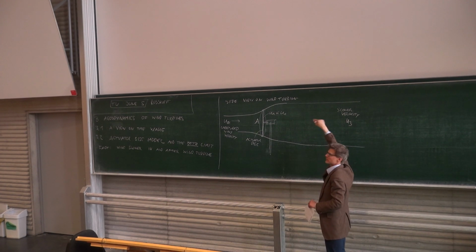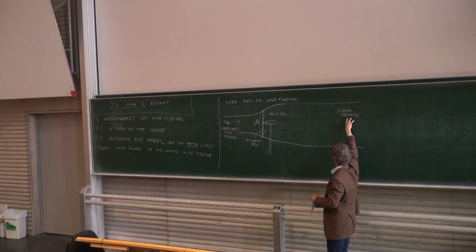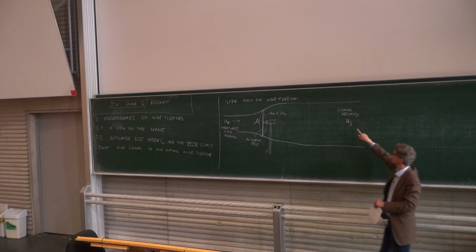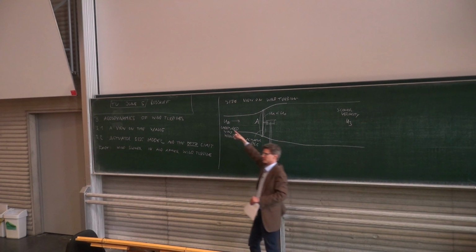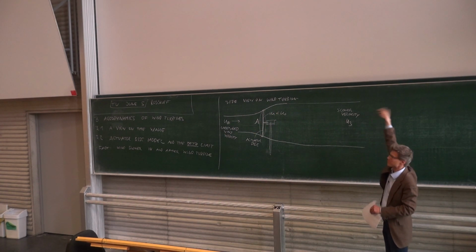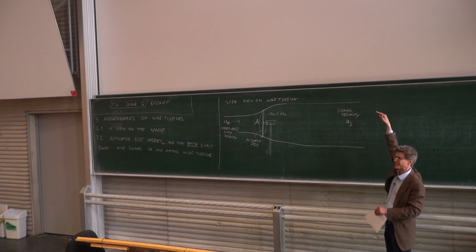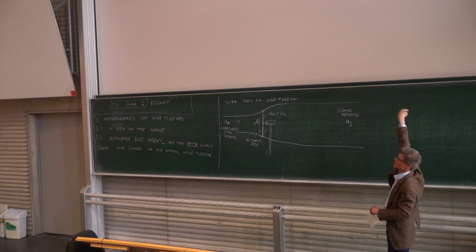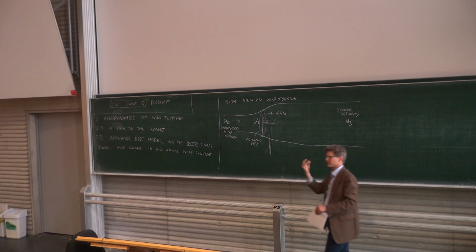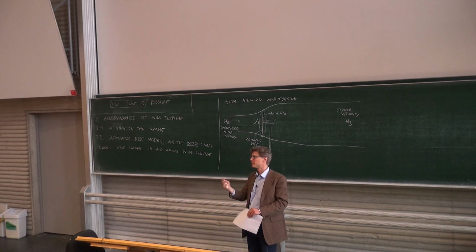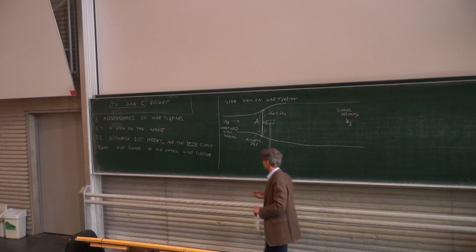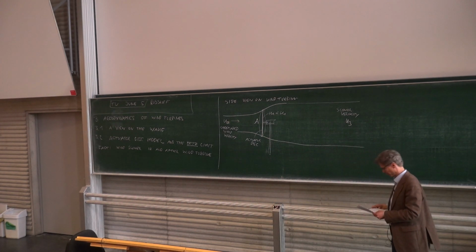Fortunately, there is some influence from the outside air and so on. If you go many times the diameter of your wind turbine downstream, at some point your velocity will again be u0 because there's friction with the outside of the wind field. In particular, from above the boundary layer of the Earth, there is always energy coming from top down, and that at some point brings all the wind again to the speed. It's the same thing when you have a skyscraper: there might be a long wake, but when you're 10 kilometers behind the skyscraper, there is nothing left. You don't see it. It's lost in the general turbulence of your wind field.